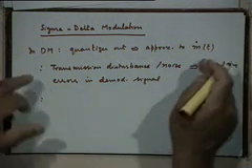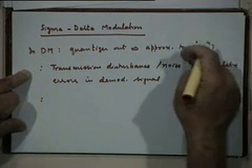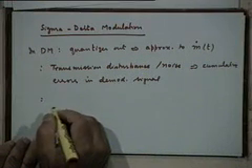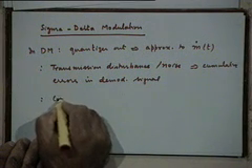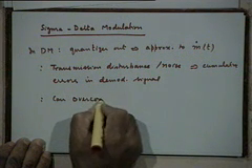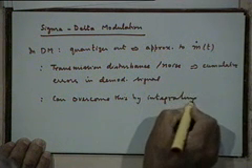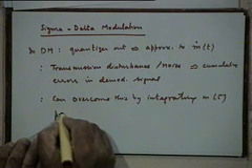We can overcome this by precisely using the same argument that we used to understand why this is a representation of m dot t. So, let us not try to approximate m dot t, let us try to approximate mt itself. How can we do that? Feed into the delta modulator not mt directly, but its integrated version, right? That is what leads to a sigma delta modulator. So, basically we can overcome this by integrating mt prior to delta modulation.